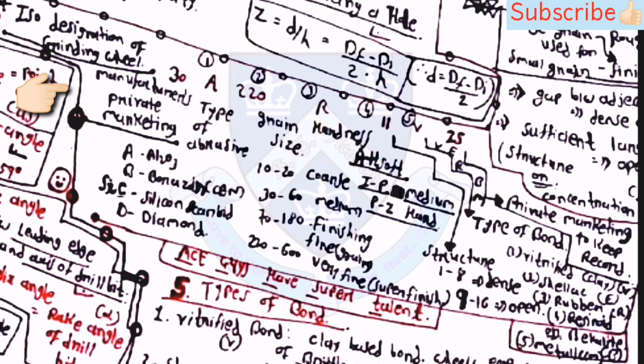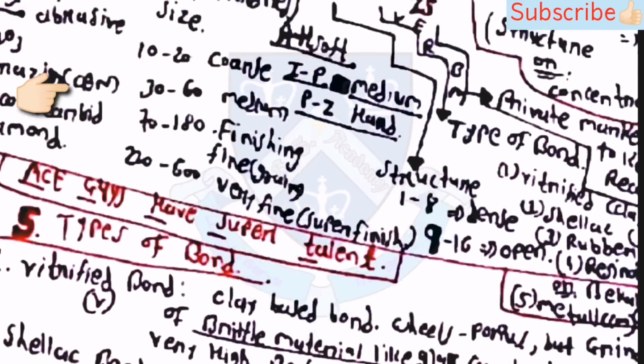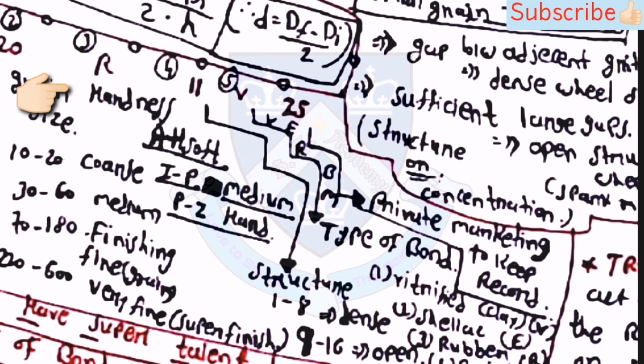In the types of abrasive there are 4 types. A is for Al2O3, B for boron nitride, then SiC for silicon carbide, then D for diamond. Then grain size 10 to 20 is coarse, 30 to 60 is medium, 70 to 180 is fine, then 220 to 600 is very fine. Then for hardness, A to H is soft, then I to P is medium, and Q to Z is hard.